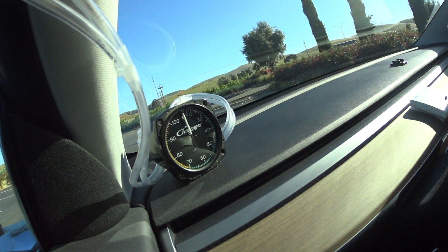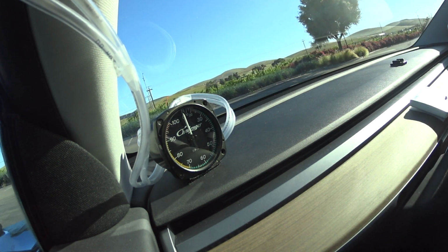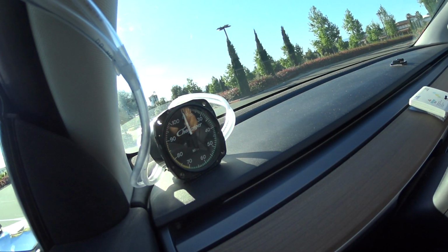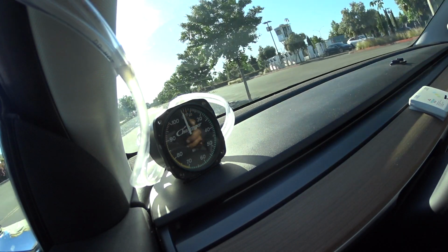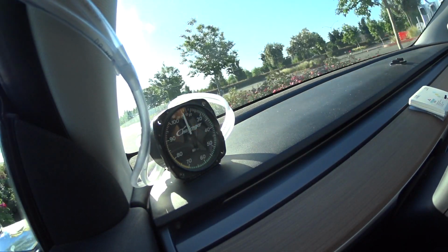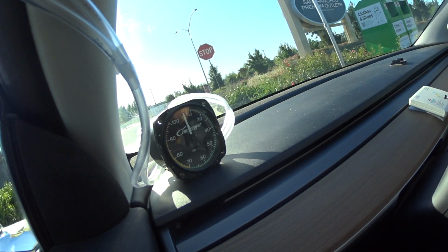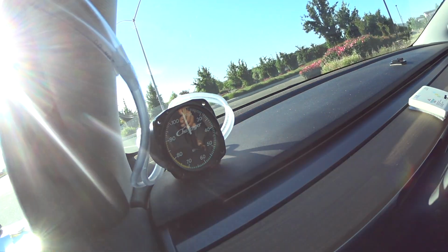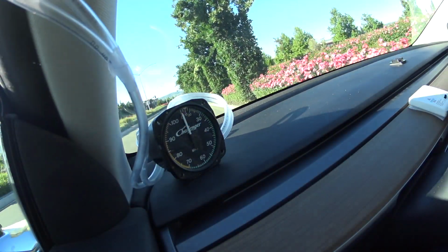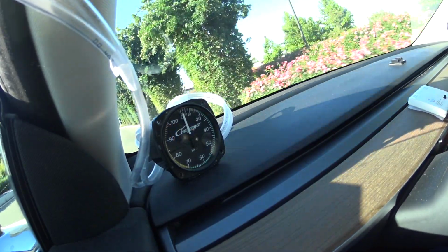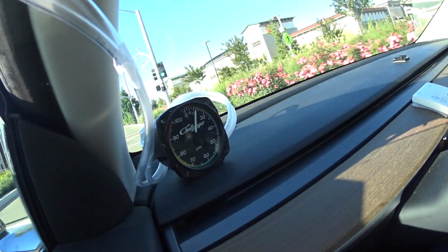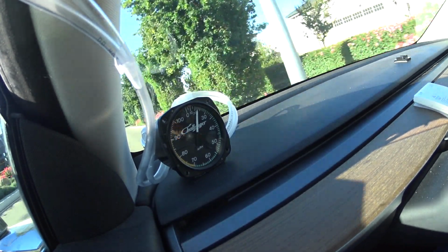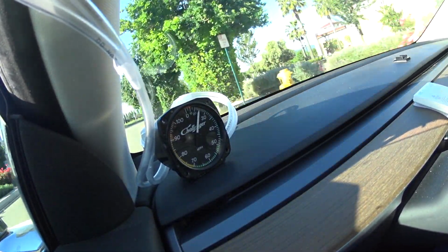Okay, so I've cleaned out the tubes, and also I did a slight pressure test on the ASI. Blew some mild pressure, used the compressor to blow some air into it. Basically I pressurized it enough to read about 100 miles per hour, close to the maximum. Did it a few times, and now it seems to be settled at 0. I'm going to see how it responds at higher speeds. It seems to be smoother right now. At least it's responding fine. And I was able to see higher speeds when I was driving back from the original place I'd stopped.